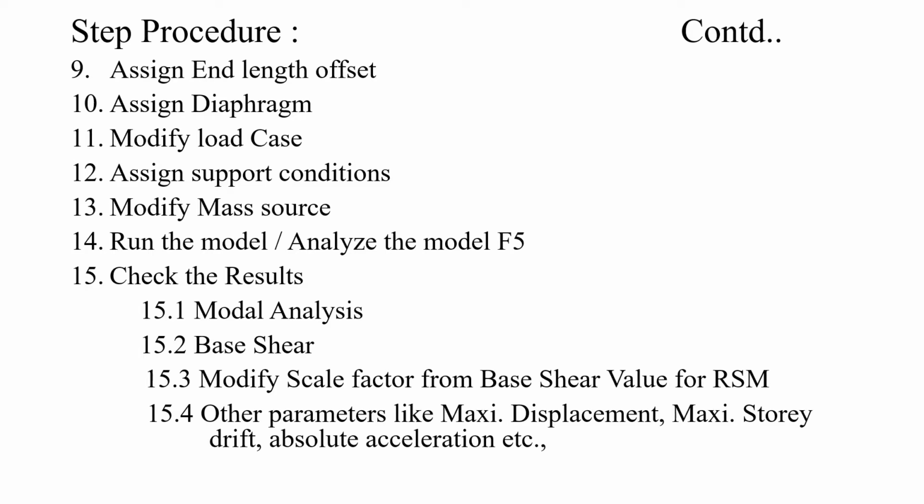We have to see for the nodal analysis, the time period, base shear, and as per IS 1893 codebook, if the design base shear of the response spectrum is less than the equivalent static method, then we have to modify the response spectrum scale factor by dividing with the equivalent static method, and the corresponding scale factor should be applied in the response spectrum load case.